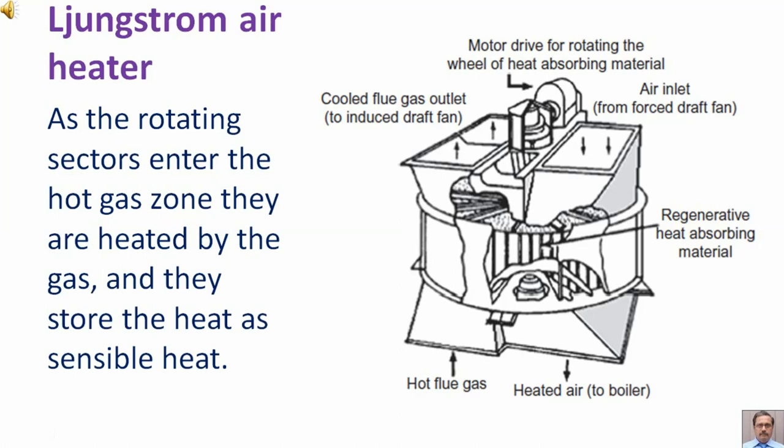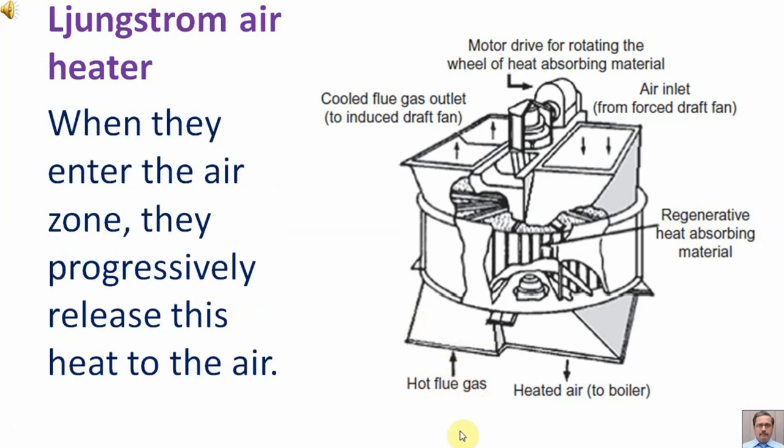As the rotating sectors enter the hot gas zone, they are heated by the gas and they store the heat as sensible heat. When they enter the air zone, they progressively release the heat to the air.